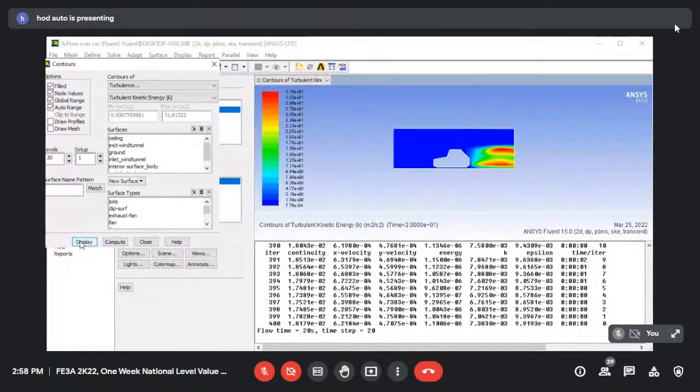By the way, please don't experiment with it. But if you observe, if you are going past a high-speed vehicle, you are being dragged into the line of direction of that fast-driving vehicle. So vehicles will lose lateral stability because of this wake. If you still want some scientific evidence on this von Karman street and the wake formations behind high-speed vehicles, just refer to High-Speed Gas Dynamics by Anderson. It's very clear.